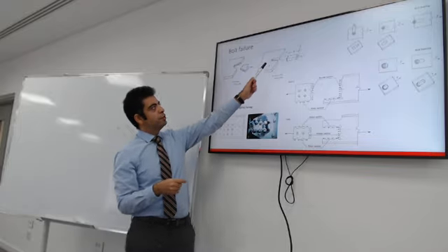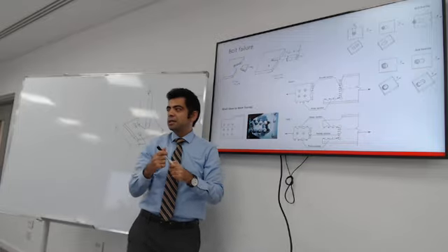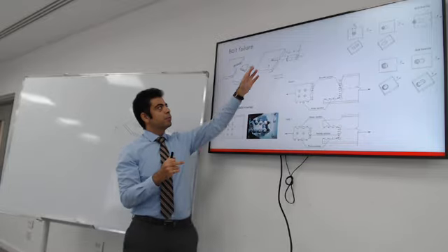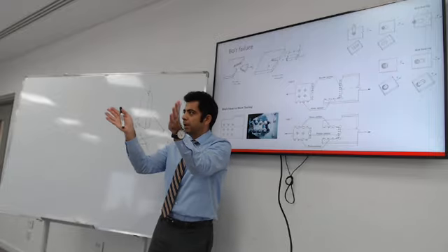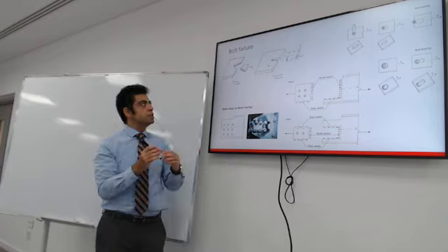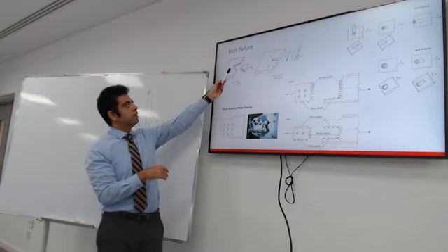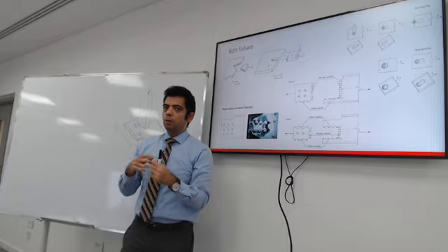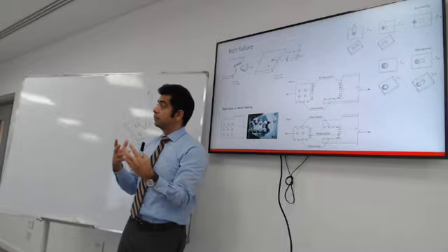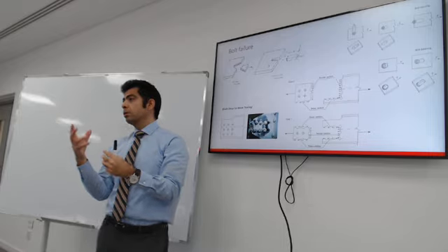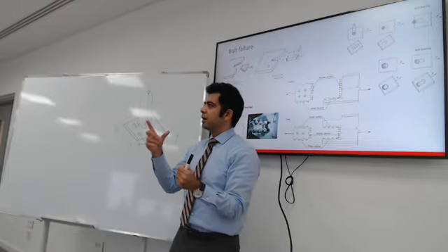This is what we assume is going to happen when a bolt is trying to pull out of the connection, but in reality it doesn't behave in straight lines like that. In reality, it will have a cone shape. It will have some angle. So which is going to have bigger resistance, the assumed failure shape or the actual failure shape? Which is going to predict a bigger failure load, actual or the assumed shape? Assumed is going to assume bigger capacity?